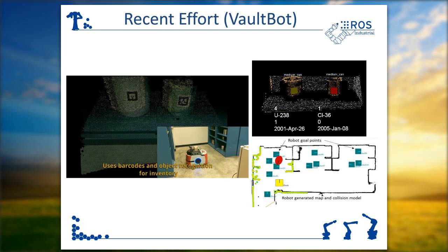A second one was a mobile system. Again, if you go to our website, I'll show that on the last slide, you can actually see videos of all this stuff. Our mobile robots are able to go in and do routine contamination testing. They're able to do inventory and inspection, cross-referencing what they see with the cameras with the barcodes to databases. A lot of the inventory inspection is actually some of the more dosage-expensive applications they have at Los Alamos. In terms of the operators, the ability to have robots go in and just say that everything is still where it was supposed to be and nothing's on the floor and nothing is hot or leaking is a huge boon to them. And we've been able to utilize a lot of ROS, NavStack, and Vision, and adapt robot capabilities for that.